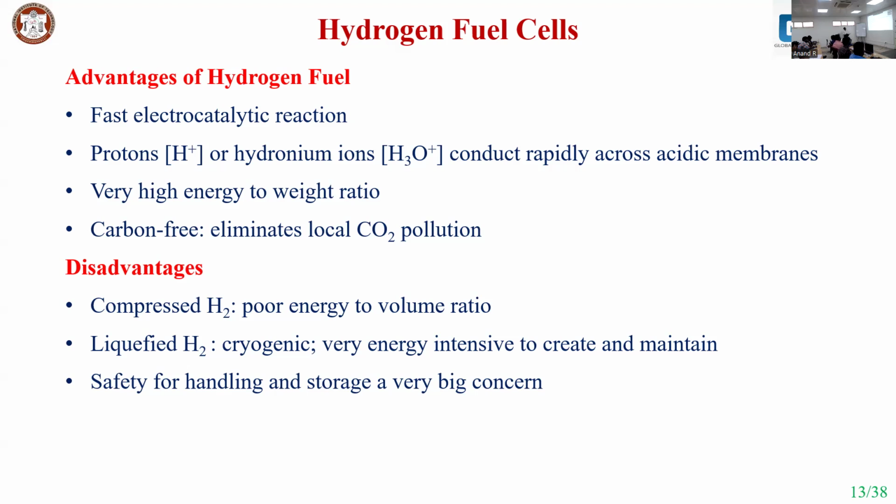And then safety for handling, because hydrogen does not create any pungent smell like ammonia. So you cannot ensure whether hydrogen leakage is happening or not, so you need a hydrogen detector. Also, the laminar flame velocity is very high, so when a fire occurs, it's very difficult to control the flame. So safety in handling hydrogen in the desired application is going to be a challenging task, because you cannot identify whether a leakage is happening.